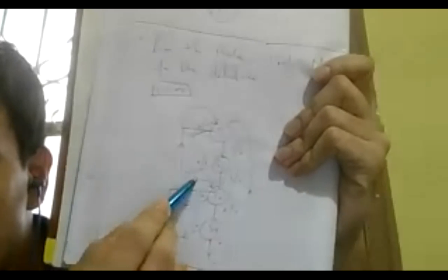So, sir, then this is state S2. The other state would be 0 by 1, and here we'll connect it back to itself. And in the last one for state S3, since we need 1, the other state is 0 by 1, so we connect back to the previous state S2 because it gives an output of 0 there only, or you can even connect to the same state S3. Yes, sir, that can also be done.